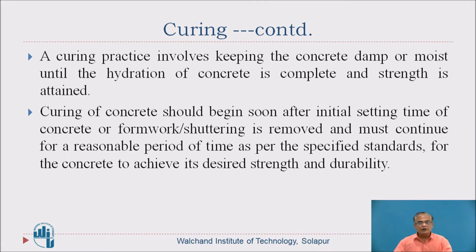Now, curing of concrete should begin soon after initial setting time of concrete, or when formwork shuttering is removed, and must continue for a reasonable period of time as per the specified standards for the concrete to achieve its desired strength and durability. Remember, curing, when should it begin?